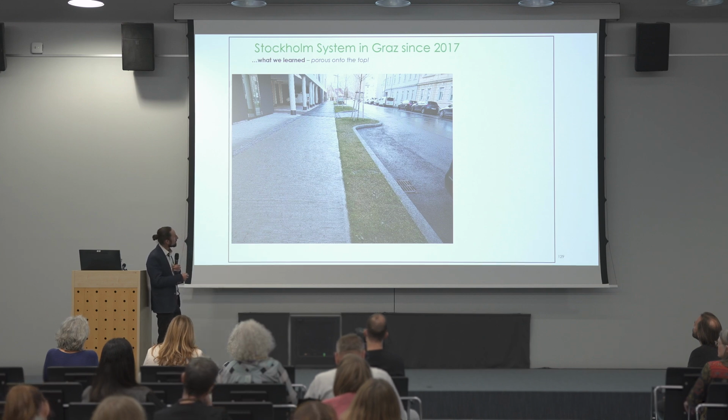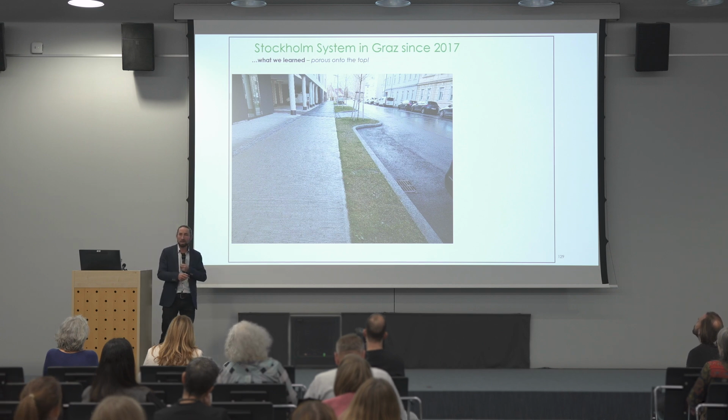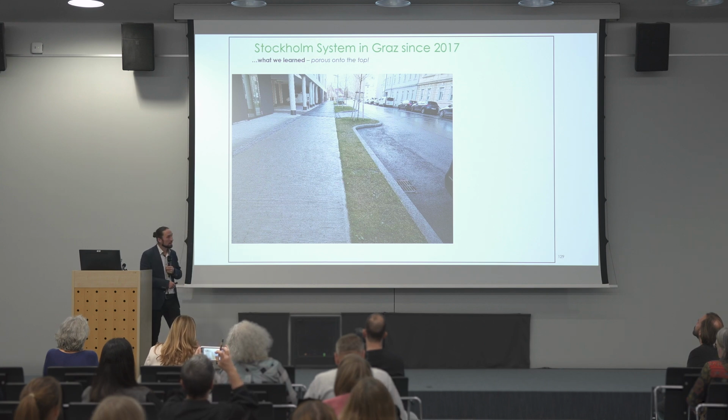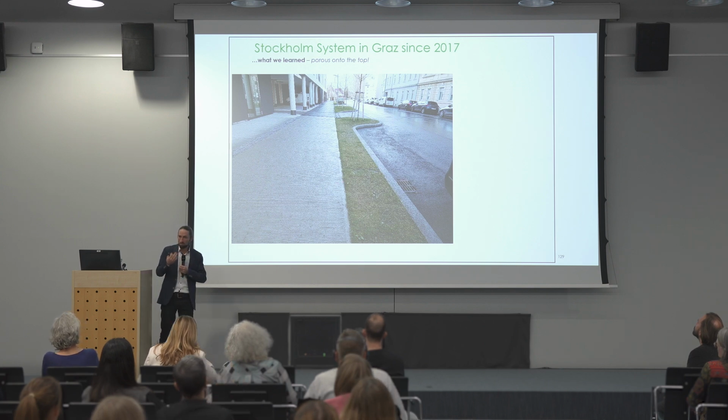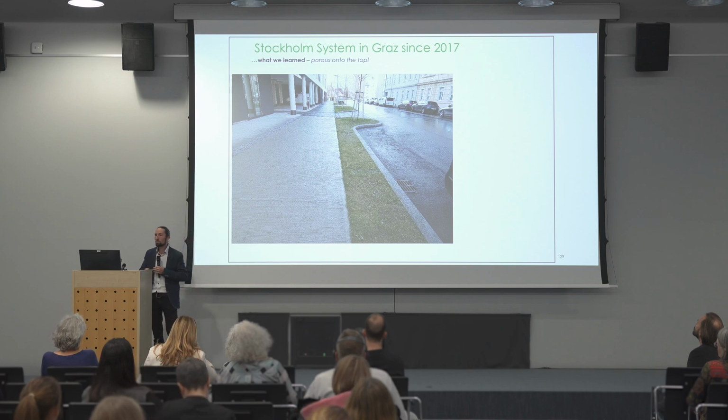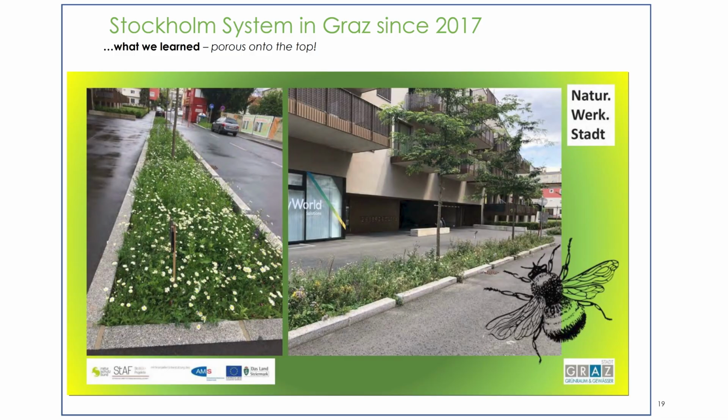So that all of the water which comes from the pedestrian area can infiltrate in this line, and the trees can also have this water, and it is separated from the outside. And when people get out of the car and walk over the meadow, there is not such compaction, because the gravel can distribute the compaction better. Or also this example, as I showed before, these are also really, really coarse substrates. There's only gravel with 4 volume percent of mature compost, and not more.